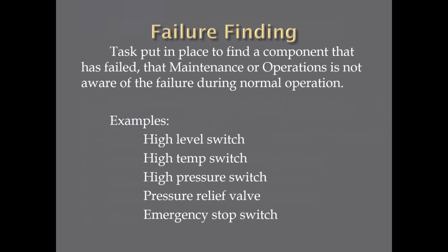A high temperature switch. How do we know the high temperature switch is going to activate when it needs to? High pressure switches. When the pressure gets up to a certain point, how do we know that switch will actually function? The pressure relief valves on your boiler. They're all set at, maybe they're set at 220 PSI. How do we know they'll actually relieve? Emergency stop switches are another example. A lot of plants I go into, I've seen up to 6 or 8 emergency stop switches on one operation, depending on where the operator's at. How do you know that switch will work? If the operator gets a shirt sleeve, drops a tool, how do we know that switch is going to work? Well, the only way we know these are going to work is to actually test them.